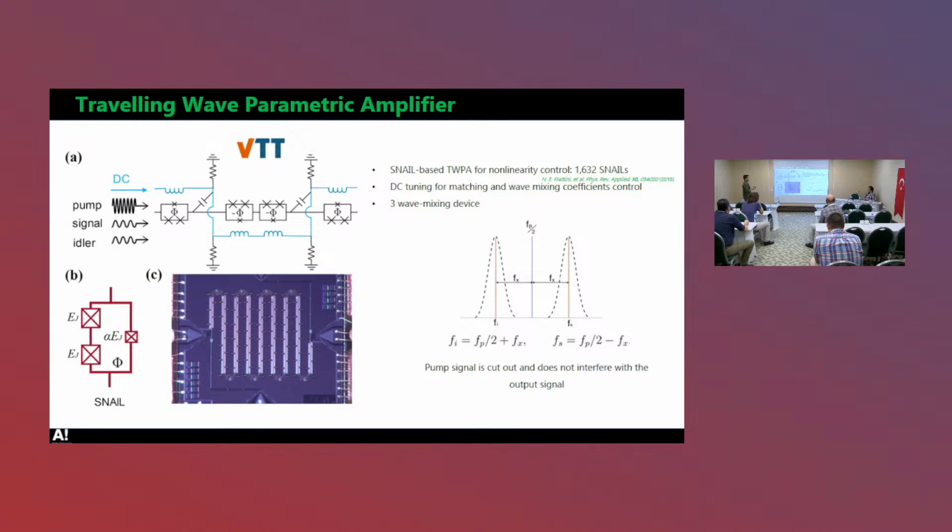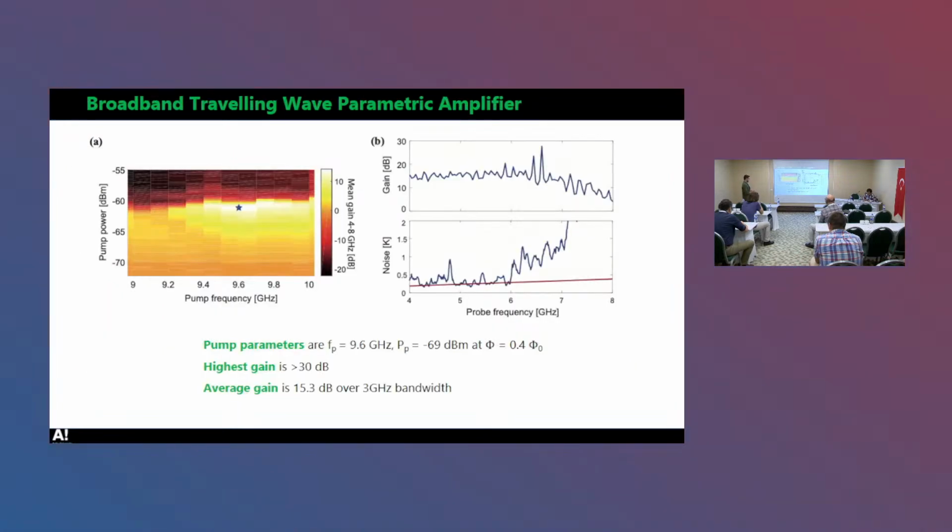We designed, or not we, but actually VTT designed, a device that is based on three-wave mixing again. Here you send the pump with a frequency twice the signal frequency. And then again, you can have the same effect as you observed in Josephson parametric amplifiers. You apply your pump, and at half of the pump frequency you have signal and idler, and they could be entangled.